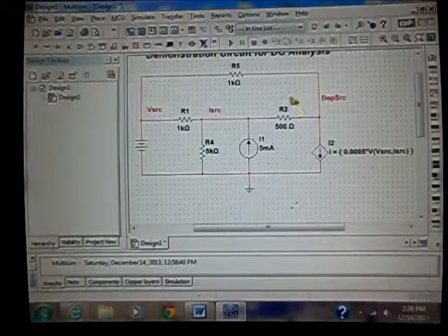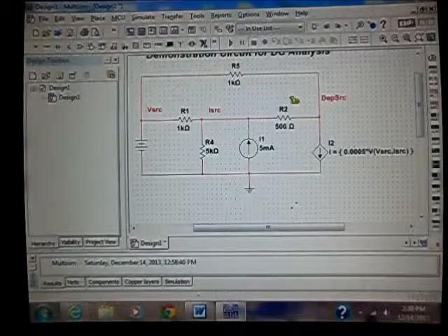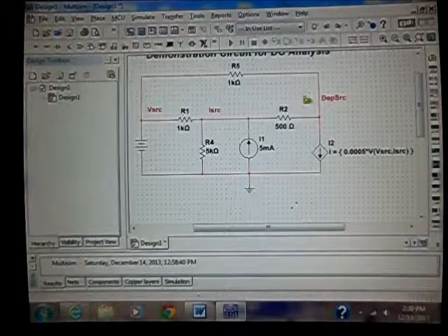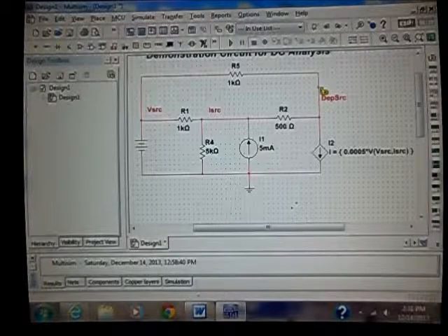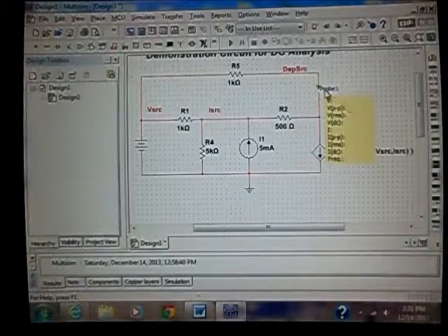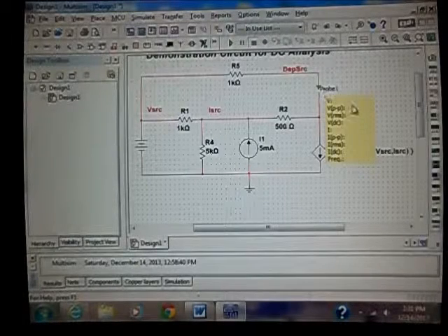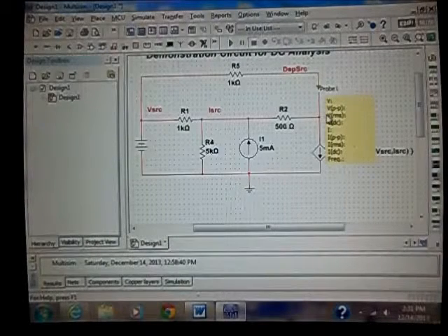And clicking on that, I bring up this little yellow thing. Let's say that we want to measure the current downward right here. So I bring the measurement probe close to that, and I get a little arrow pop up on the wire. Then left clicking deposits the measurement probe. Now that's going to measure the current downward as well as the node voltage here with respect to ground.